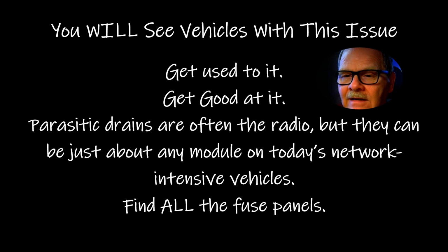Now, any module on today's network intensive vehicles can be a battery killer, and relays can stick and cause the batteries to die and all that. So I could go on and on about this.